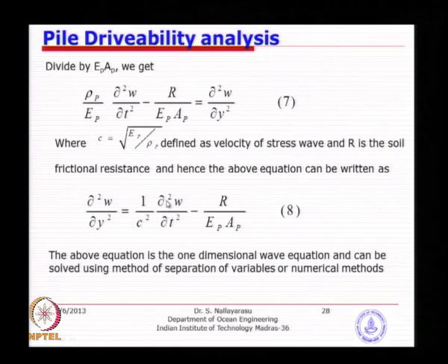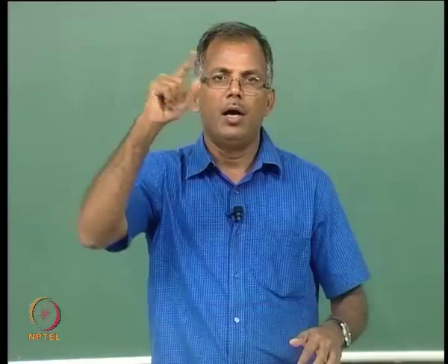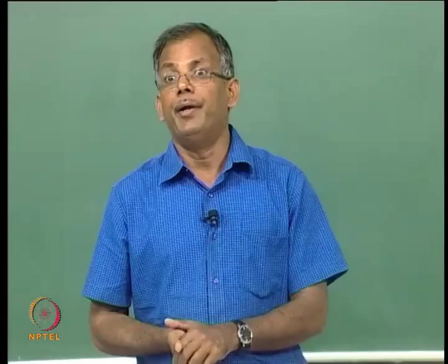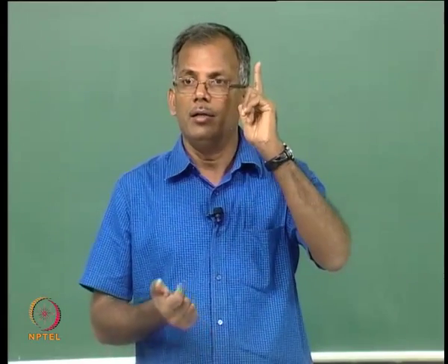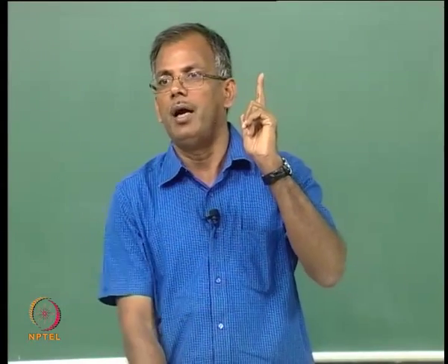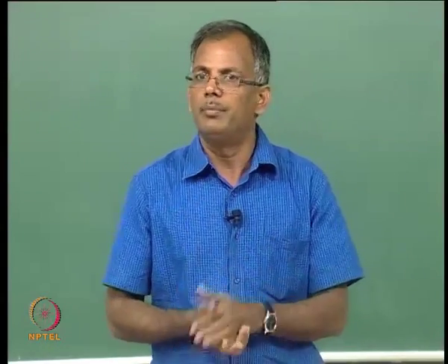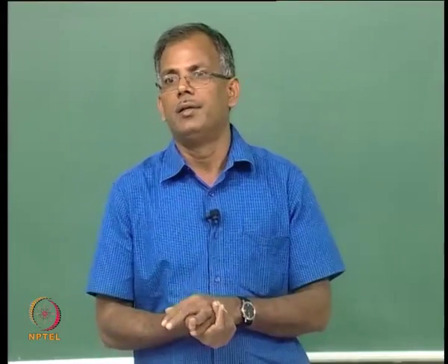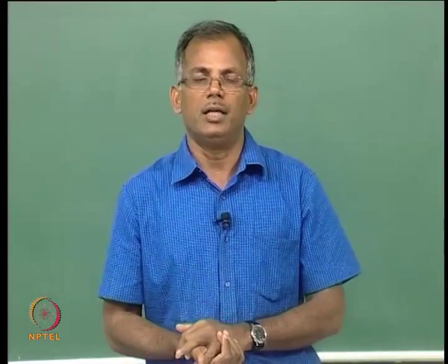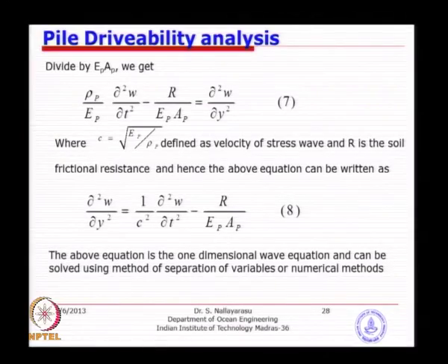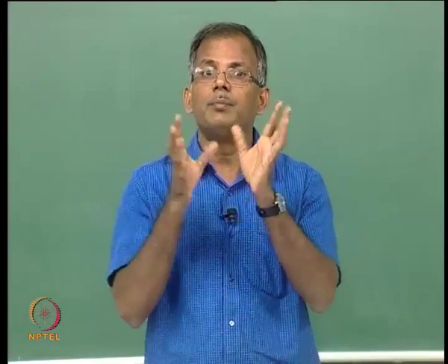And we need to find a solution to this, because what we require is, just after one impact, the displacement pattern along the length of the pile, and during the time until the stress wave goes down the pile to the soil and reflects back. So we need a time history of pile movement, pile acceleration, pile velocity for every impact, and that is the idea behind it. And you can actually solve using method of separation of variables if you have simplified conditions.